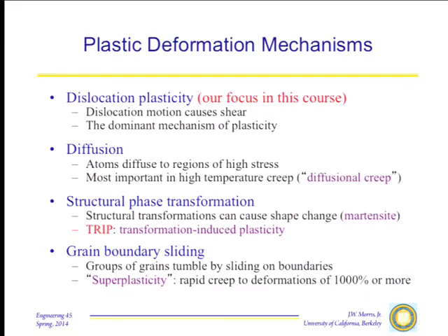In fact, you can prove thermodynamically that there is no such thing as a solid. You know, the definition of a liquid is that it takes the shape of its container. So will a solid if you give it enough time. Because thermodynamically, the second law tells you the evolution of the material will be toward a shape that is most compatible with the applied stresses, which will be fitting its container. And there exist mechanisms, such as diffusion, that may take more than the lifetime of the universe to accomplish that, but will eventually accomplish that and cause the solid to behave like a liquid. So in a sense, because of these mechanisms, there's no such thing as a solid. We don't have to worry about that most of the time, but it is true.